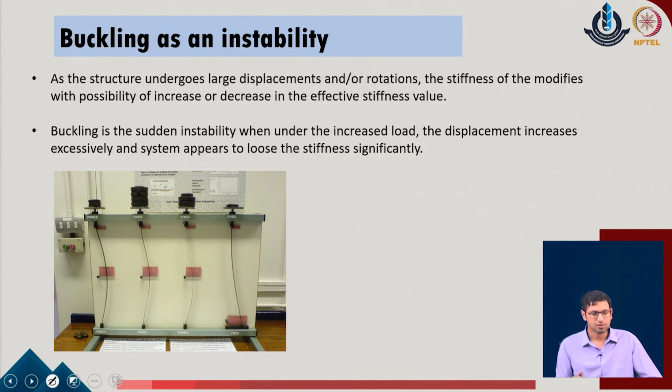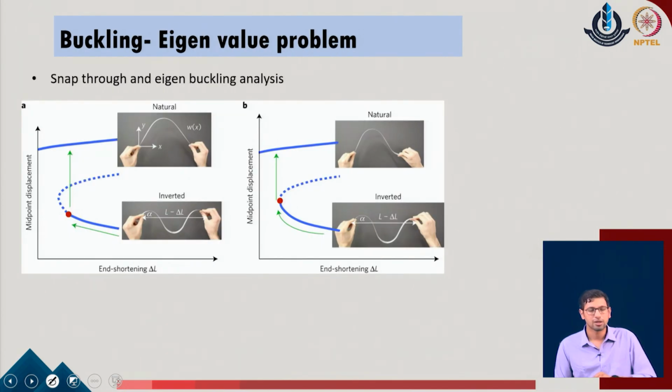As a very simple case of the analysis, we have already highlighted that we typically consider the stiffness of the given system as reducing significantly, and the system may undergo large deformations. If those deformations become significantly large, where there is no control on the possible displacements taking place, we typically identify that the system has reached a failure mode or a buckling mode.